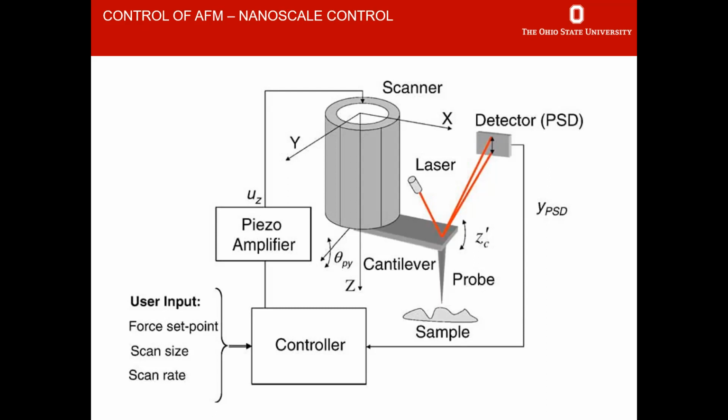The model is different, and the actuation is quite different. This is from atomic force microscopy. This is nanoscale control. So this is a quartered piezo, which means it's a tube divided into four quarters, and if you apply the voltage source accordingly to these different quarters, you are able to bend the whole thing, such that you obtain nanoscale motion, which is neat. You can use this for characterization of surfaces, but also for manipulation at the nanoscale.